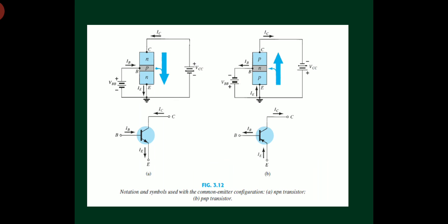And now to make junction JC reverse biased, the p-type collector region is connected to the negative terminal of battery VCC. VCC is the voltage source. The VCC represents double subscript notation here, right? So the positive terminal of VCC is grounded. So what is VBE then and what is VCE then?